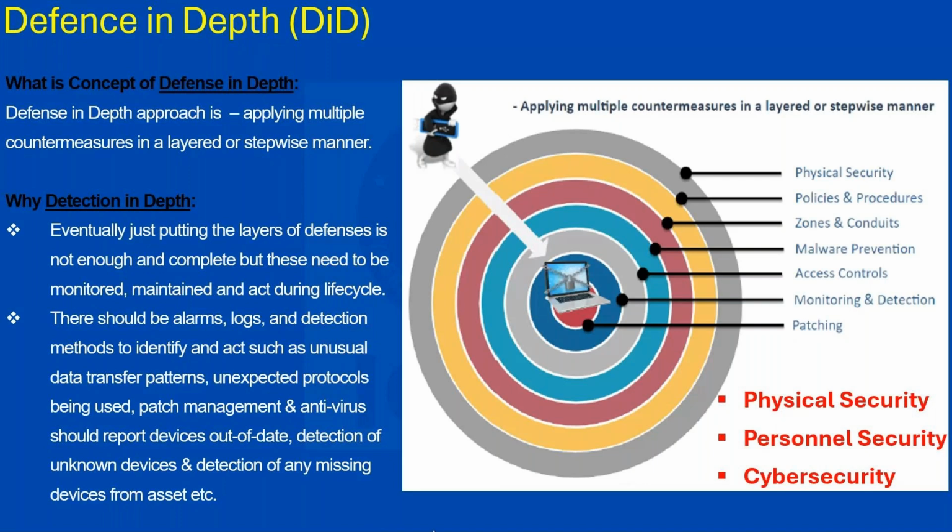Patching. In IEC 62443, one particular part itself defines a dedicated technical report, which I hope very soon is converting to a standard. There is a dedicated way of patching. There is a complete life cycle of patching in OT: the identification, the testing phase, the deployment phase, the stakeholder engagement. I think there was one very famous incident recently where an airport was badly impacted. Some sort of issue was highlighted. I don't remember the exact name of it, but what I'm trying to highlight here is that patching is very crucial, because it also demands maybe a reboot, a restart, or some sort of response time.